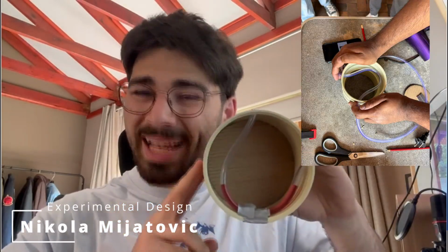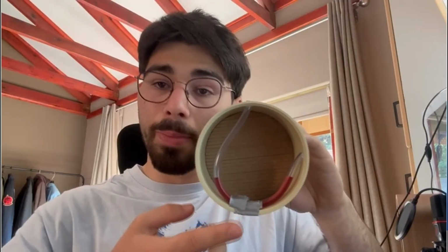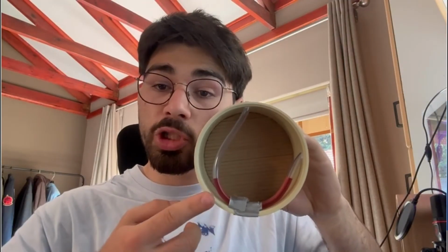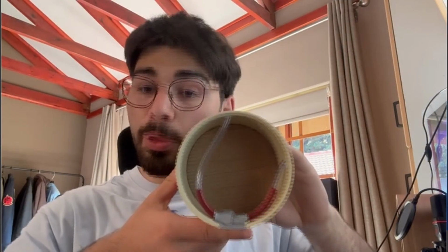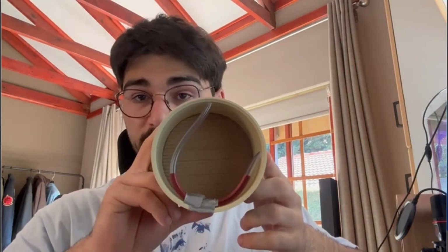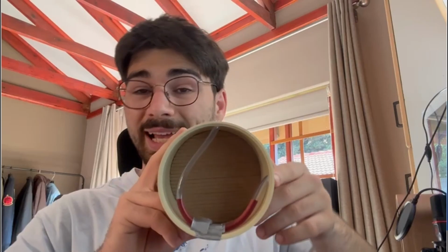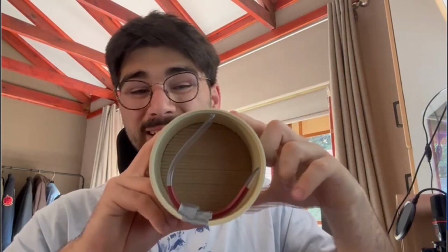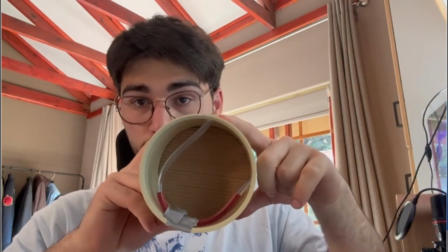A smaller demonstration model was constructed to clearly illustrate the design and function of the experimental setup. This compact version consists of a horizontal pipe with a U-tube manometer connected, which is partially filled with red dye, allowing us to view pressure differences easily. One port of the manometer faces directly into incoming airflow to measure the stagnation pressure, while the other one is flush with the top of the tube to measure static pressure.